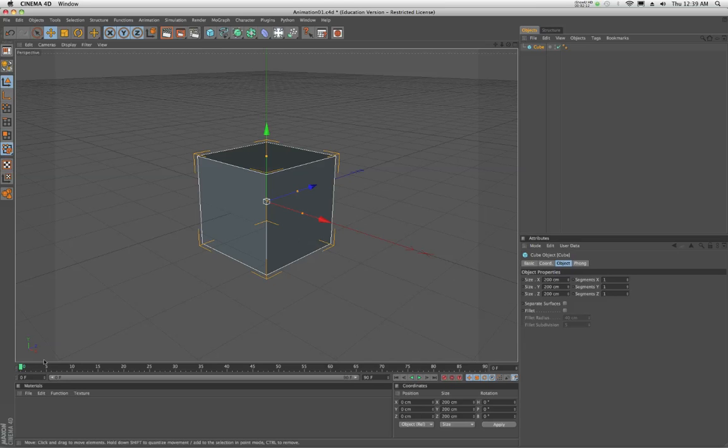We'll talk a little bit later in detail about the relationship between the number of frames and frame rates and all the things that we want to keep in mind. But for now, all that we need to be concerned with is that by default, Cinema 4D is playing at a frame rate of 30 frames per second. So up to frame 30, that amount of information plays in 1 second of time. Okay, so with 90 frames of information, Cinema 4D is currently set to play for 3 seconds. So any animation that we create over the course of 90 frames will take 3 seconds to play, and that'll sort of be the standard for this class.